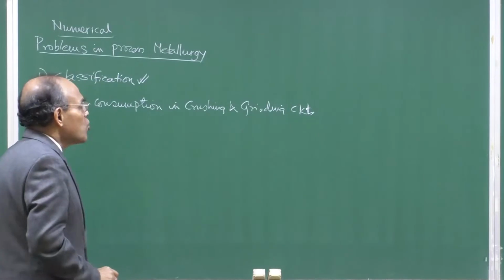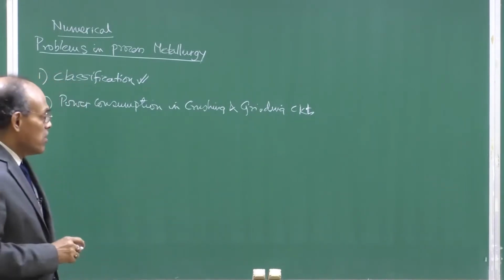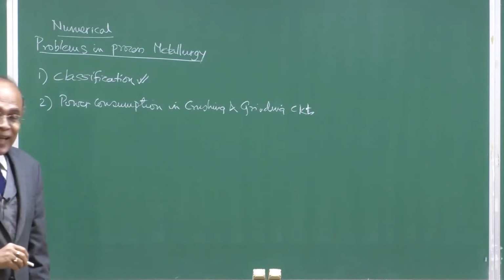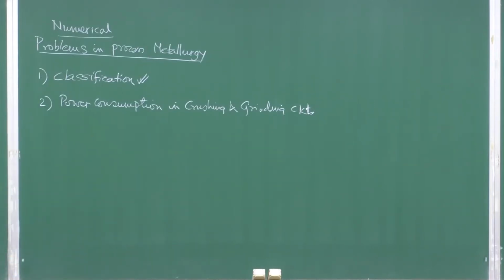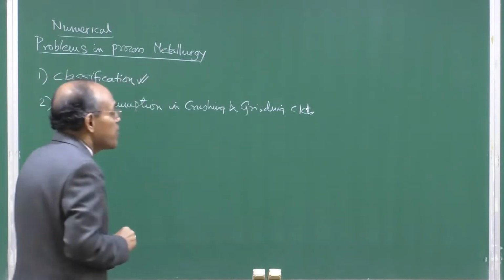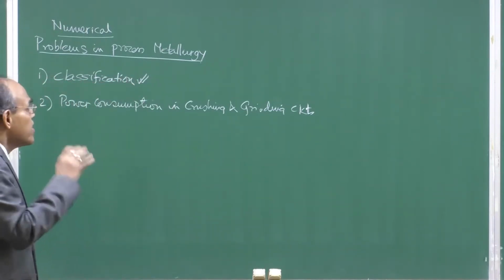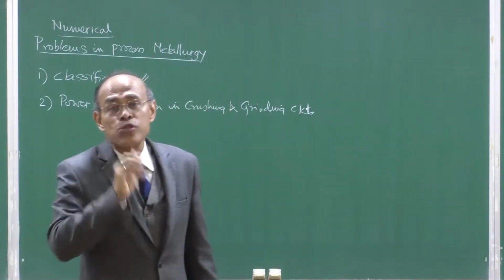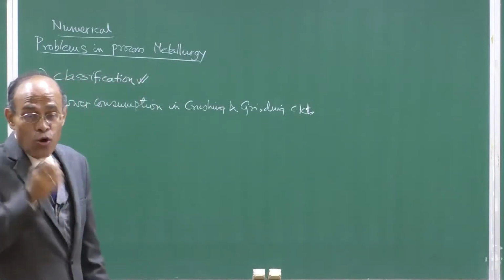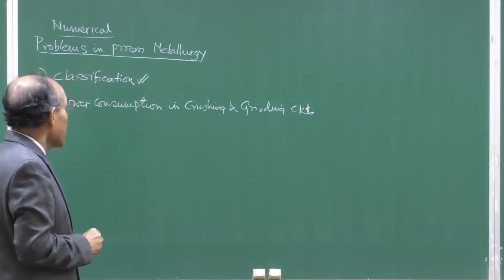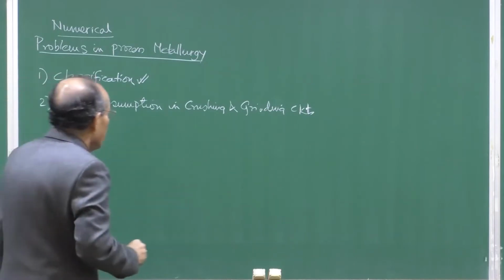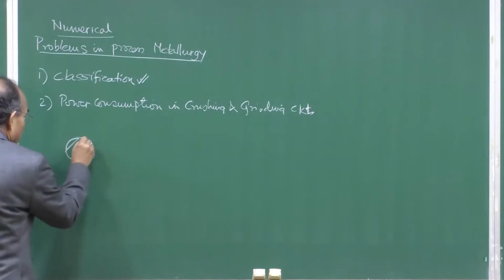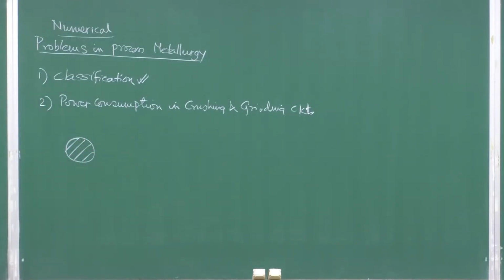Now, most of the time these classification theories or free settling theories are derived on the basis of laws of settling, which are derived essentially from force balance equations, and in this context the most elementary and simplified one is the Stokes law of settling, and Stokes law also most of you have come across. So, basically the Stokes law, as you all know, talks about settling or rising of a spherical particle, okay.